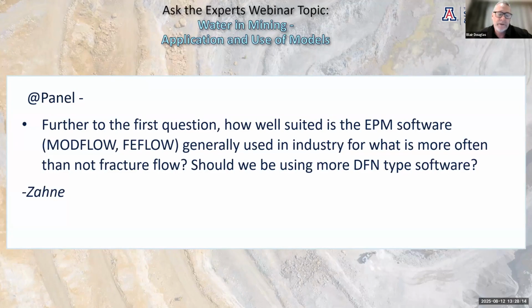So it's back to what I think, Ian, you spoke about, scale and getting down to the right level of scale. But it does also depend on what you're trying to achieve and what the geotechnical need from the model is. Because if the geotechnical model has a sensitivity to pressures of, say, 50 meters, and your numerical groundwater model has an error over that, it's essentially useless.